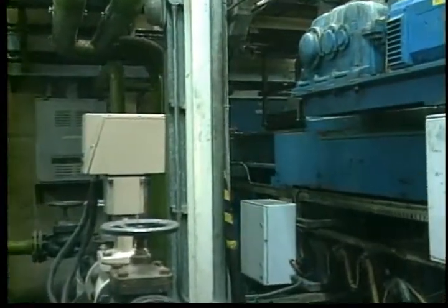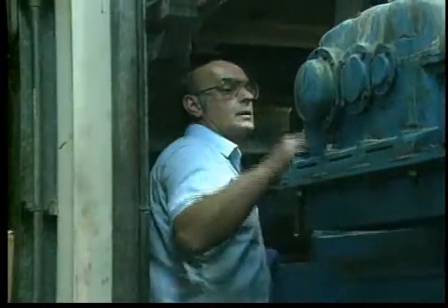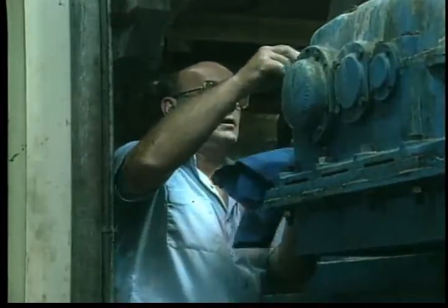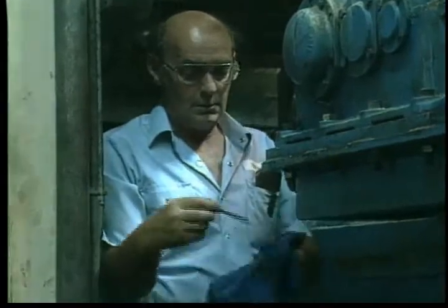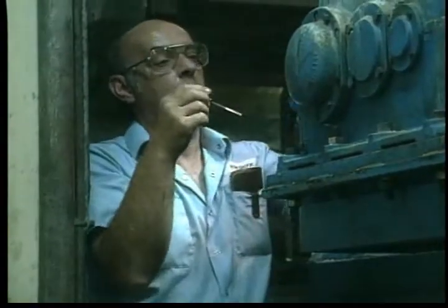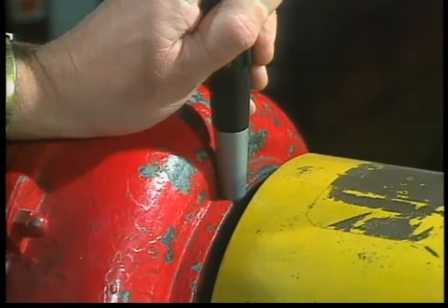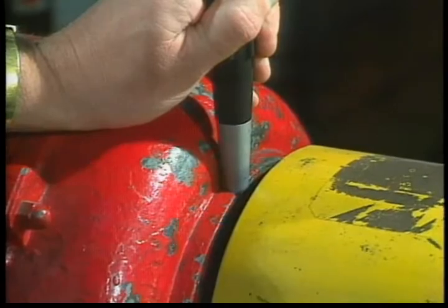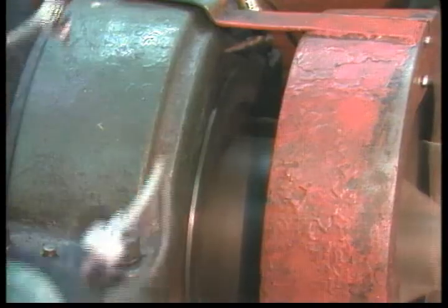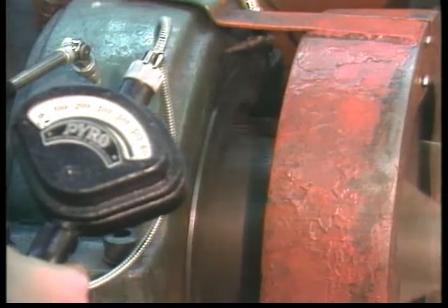In some systems, the lubricant is circulated to remove heat. If the oil seems to be at the right level, but operating temperatures are higher than normal, check to see if the oil is actually circulating. A blocked breather hole can sometimes result in false readings of the oil level. Tools such as this temperature probe will make checks of bearing temperature quick, accurate, and safe. Some bearings run hot enough to burn you, so using a probe is safer than touching the bearing housing.